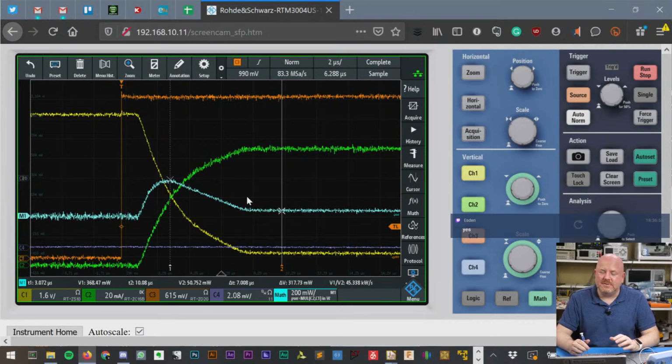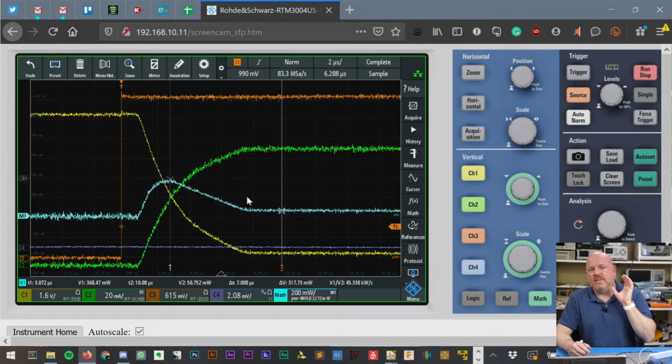Probably. Should you? I still think you're going to want something on the order of 10 to 100 ohms. That's why I say this is going to be a cliffhanger, because the next step I want to do is make those measurements, since that's a more realistic resistance value. You really wouldn't put 3K ohm on a gate. That's just too many ohms. And I know I like to say you should add ohms. Sometimes you should only add as many ohms as you need. Okay.